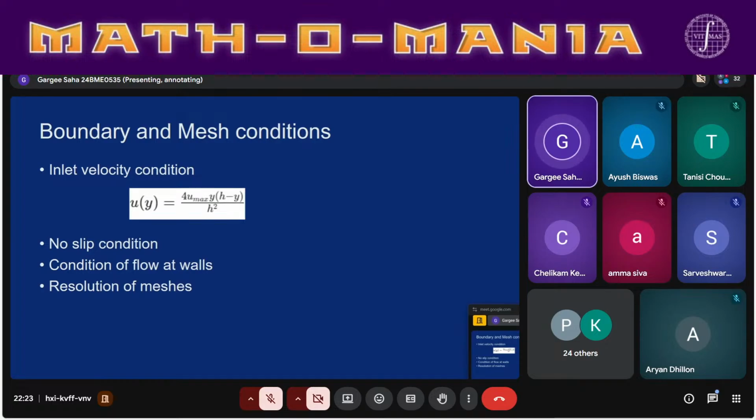So there can be a lot of different cell types in 2D meshes, which we will see in a bit. We can have quadrilaterals or triangles, or even polygons of more sides if we want to get finer or rougher grids. And in a 3D mesh, these cell types are usually hexahedrals, tetrahedrals, or prisms.